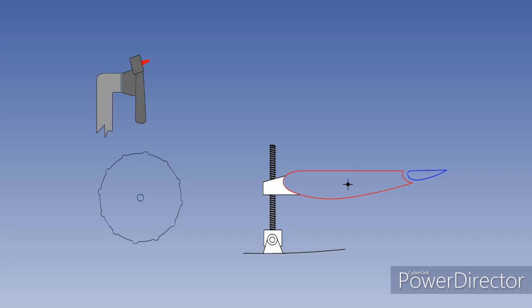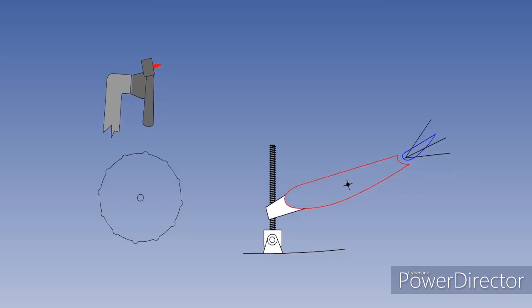The second advantage of the variable incidence trimming tailplane is that there is less aerodynamic drag when the aircraft is in trim, a big advantage in the cruise. The third advantage is that trimming does not reduce the effective range of pitch control. As before, the total range of the elevator is limited by the primary stops. But because the elevator is faired with the tailplane when trimmed, both full-up elevator and full-down elevator from neutral is always available to the pilot for pitch control.